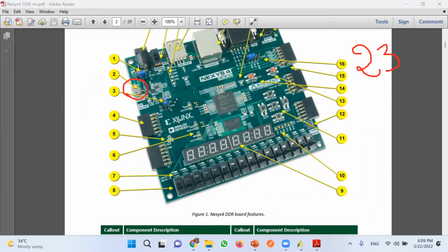So you have the data cable with your kit. The USB connectivity you have to connect to the PC, and the remaining connectivity, that is the OTG connectivity, you have to connect here at port 2. This is a very important one. After connecting your data cable here, you have to switch on the power supply. When you switch on the power supply, it will automatically switch on the kit, and one default program will run. That I will show with a video. Presently these two are very, very important.